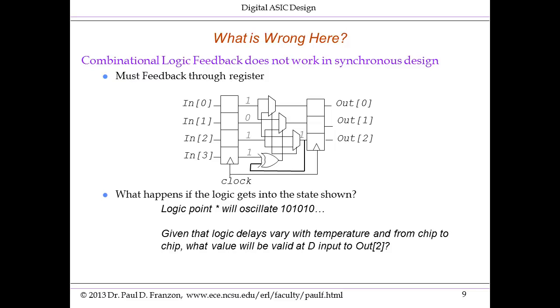And by the way, in coding RTL, it is common to accidentally do this, so that is, unintentionally create combinational logic feedback. We'll be talking about that later. So that's the point. You don't know what the value of out2 will actually be.